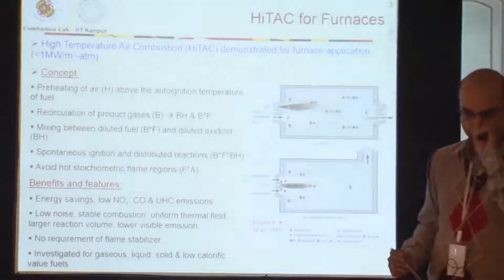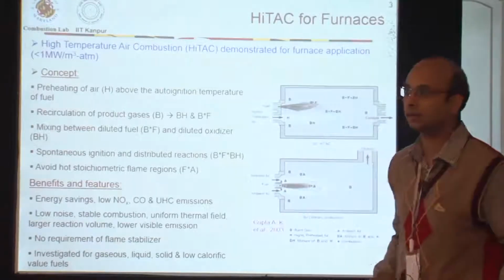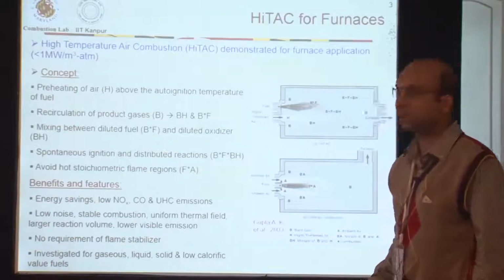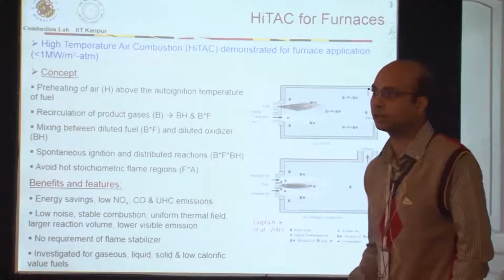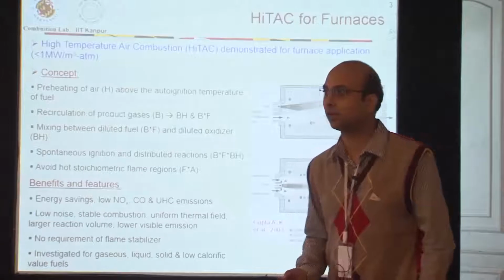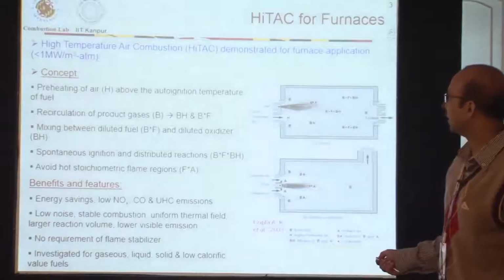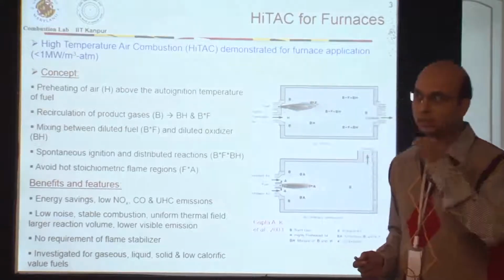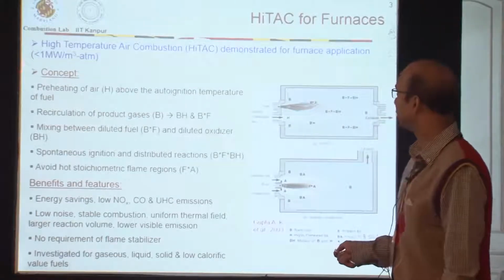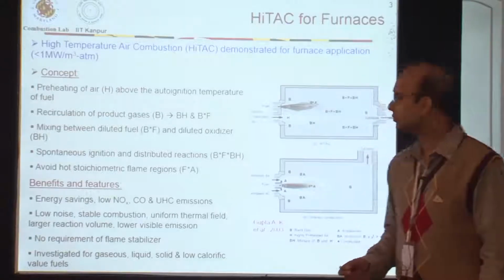So high temperature air combustion, the work started in early 1990s. It has been almost 25 years now, and it was successfully demonstrated for furnace application. For furnaces, one important thing to note is that they have large volume, so the amount of heat released per unit volume is pretty low, mostly less than 1 megawatt per meter cube.